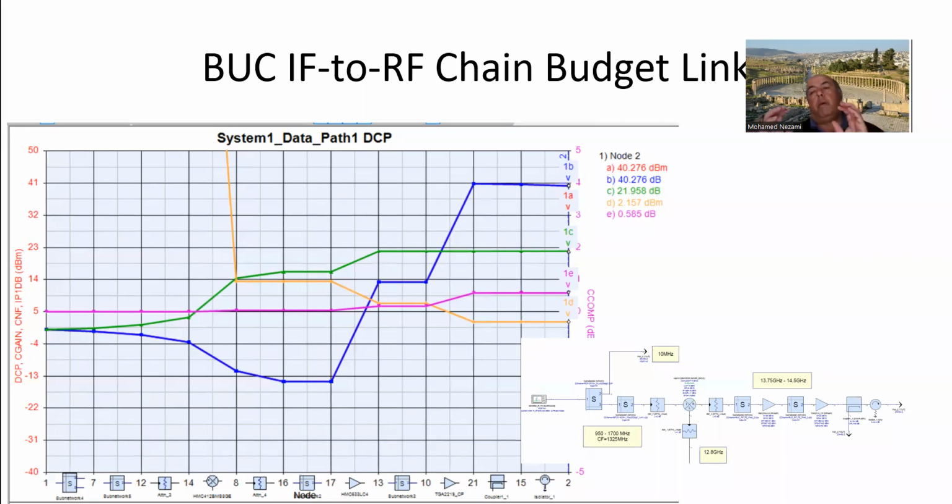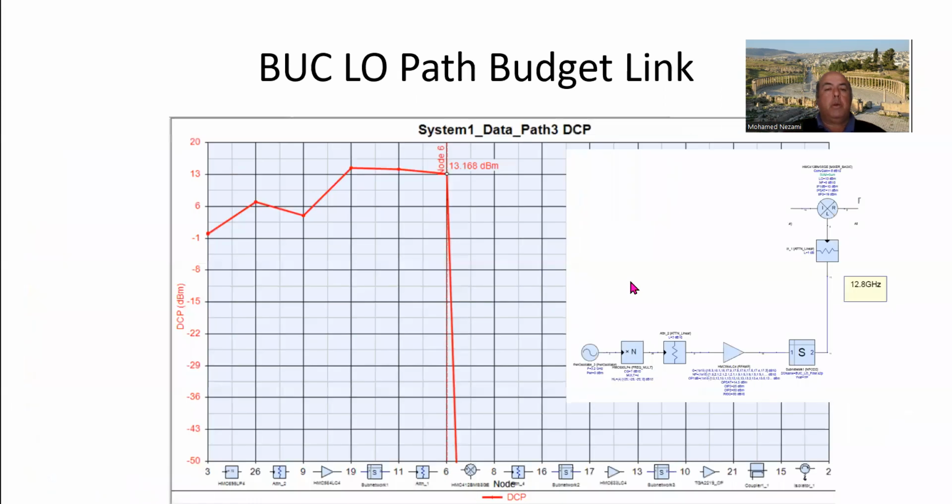But now, this is really fictitious because as soon as you put an amplifier, if you were to go back from the DAC that generates the IF signal, then obviously there you establish the noise figure, which will be more reasonably between say 5 and 10 dB. That's okay for a transmitter, okay?